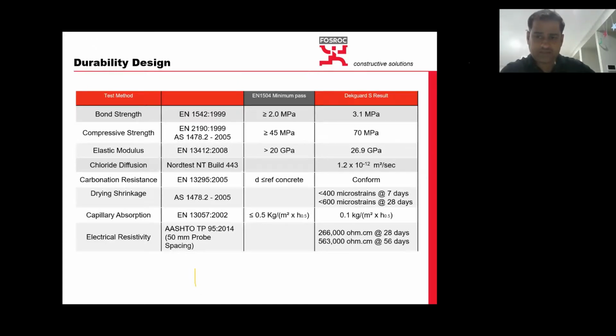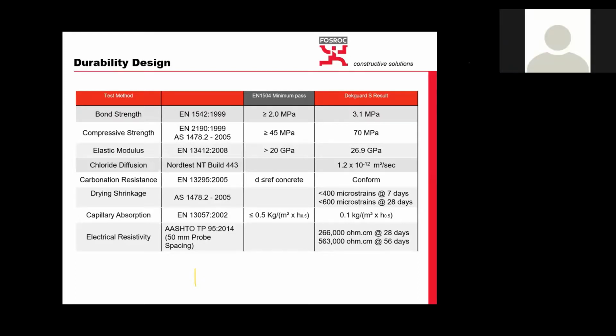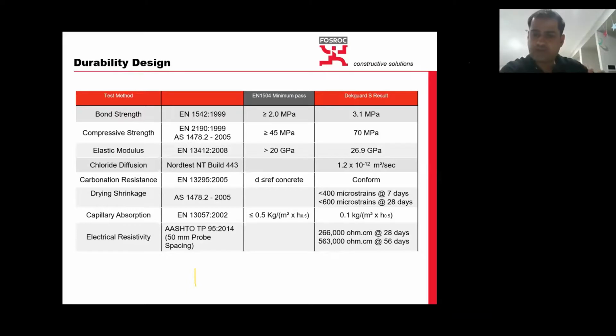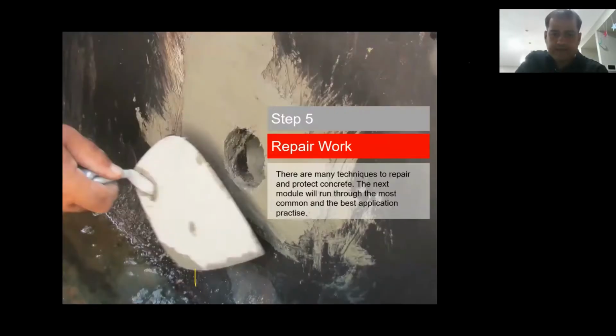One thing is very important, I think I should mention here, and I've seen a lot of engineers struggle with this. For large refurbishment projects, if a product says that it has a bond strength of 3 MPa adhesion, pull-off, that doesn't mean that at site it should give that 3 MPa value. This 3 MPa is as per, for example, Australian standard or EN 1542 standard. At site, VicRoads and some other engineers say that 0.7 MPa is good enough, with none of the values less than 0.65 MPa mean values. So when you are doing a site trial sampling and a pull-off test, it's a bit different than the laboratory controlled bond strength testing.